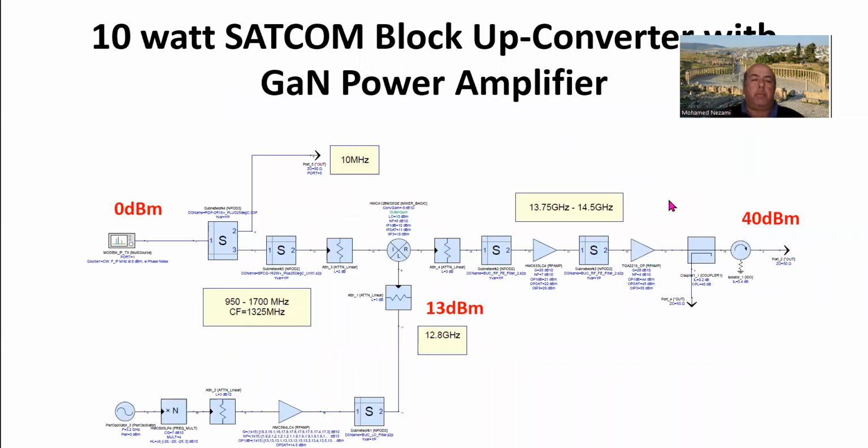So back to my system now. So we're going to simplify this. So we know that we have 0 dBm from the L-band modulator. We want to take that into a duplexer to split off the 10 megahertz one way, and the IF another way, and then we're going to filter, pad it down, and then go into the mixer, mix with a synthesizer at 1/4 of the frequency.